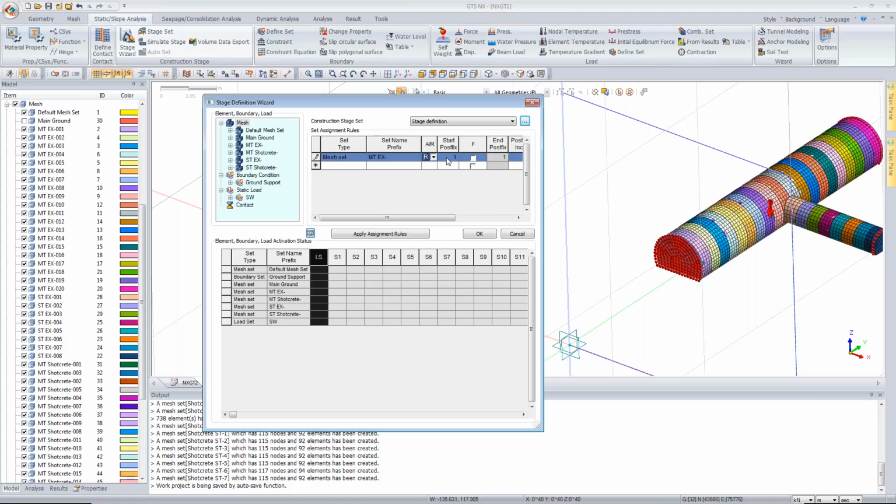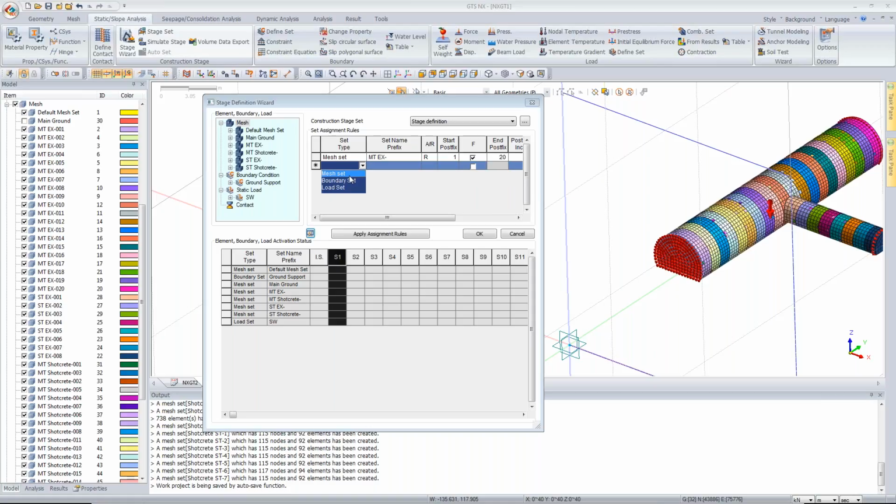Start postfix we have named it properly, so it will start from 1. Okay, and end postfix you have 20. Fine. So postfix increment, so 1, 2, 3, it will go one by one. Start stage is 1, we'll start from here, and stage increment is 1. Okay, with each stage we'll be moving 1 by 1, 2, 3 like that.